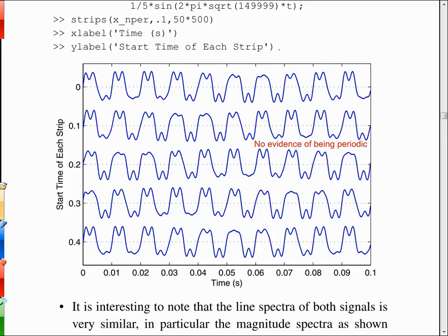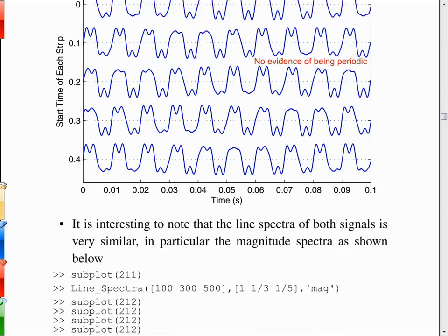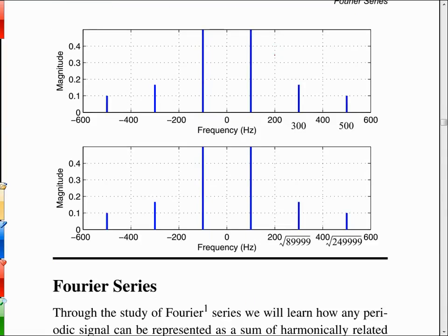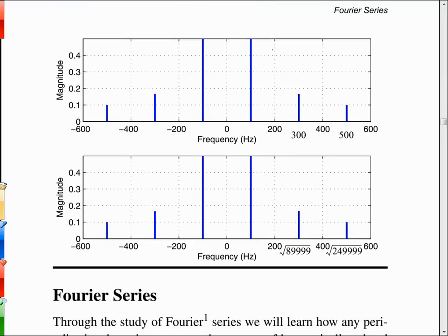In other scenarios, though, the sinusoids that would make up the composite waveform might actually not be standing at a constant frequency. They might be drifting relative to one another. Kind of like if you had two clock oscillators in a microprocessor or computer system, they wouldn't stay in sync with one another unless you phase lock them. So they would drift around, and so the waveform that would be produced if you sum those together would never be periodic, because there would always be some drifting going on. And this just shows the spectrums look essentially identical at this distance, but if we were to zoom way, way in with a spectrum analyzer, we'd see that they're not exactly equal.